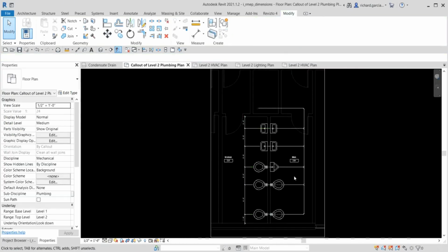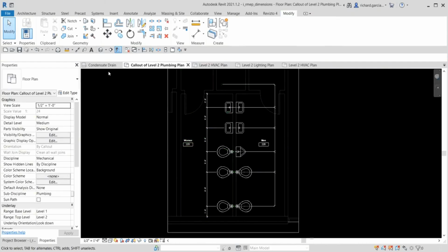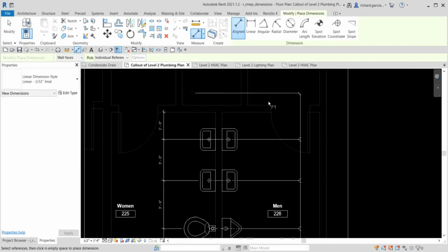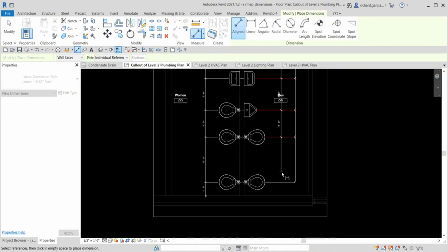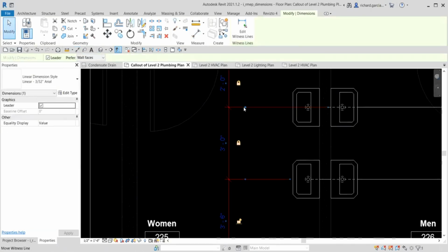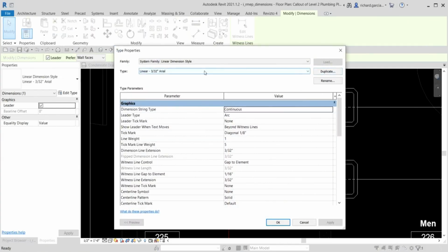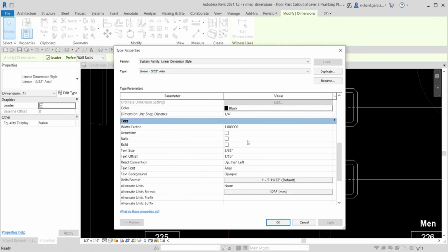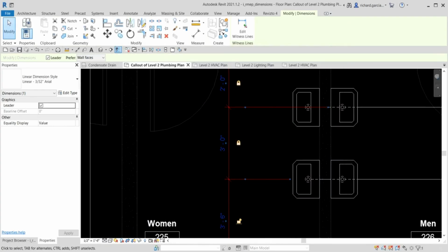Okay. Right, now if you want to do it manually as well, another way is the one that I have shown you a while ago. Just click the dimensioning tool here, and then, yeah, it's up to you. How do you want to place your dimension? So you can do it like this, or you can also do it the way I did it first, just now. You can do this procedure also. Okay, again, if you want to create a new type of dimension, so you can just select that, and then just select edit type. Same way you created the text type. So just edit type, duplicate it, change the name, and then just put the properties that you want here, and then after that, you can select OK. So it's just the same way you created the text type, all right? Okay, so basically that's how you place your dimension.